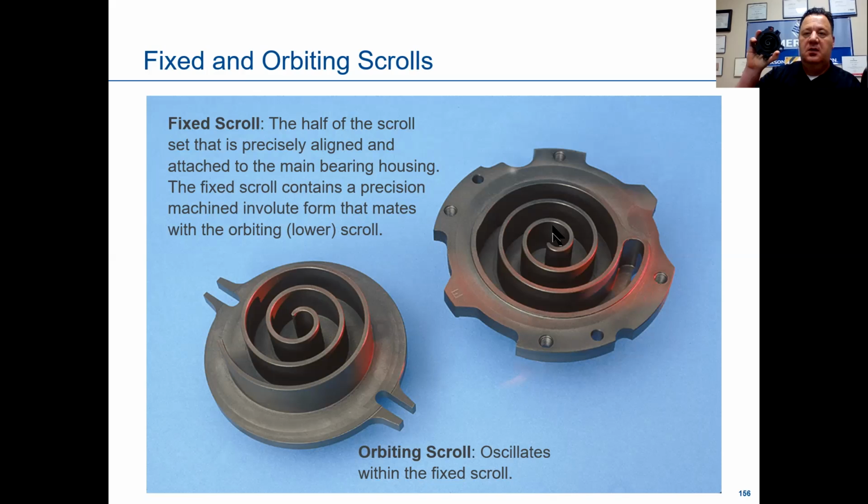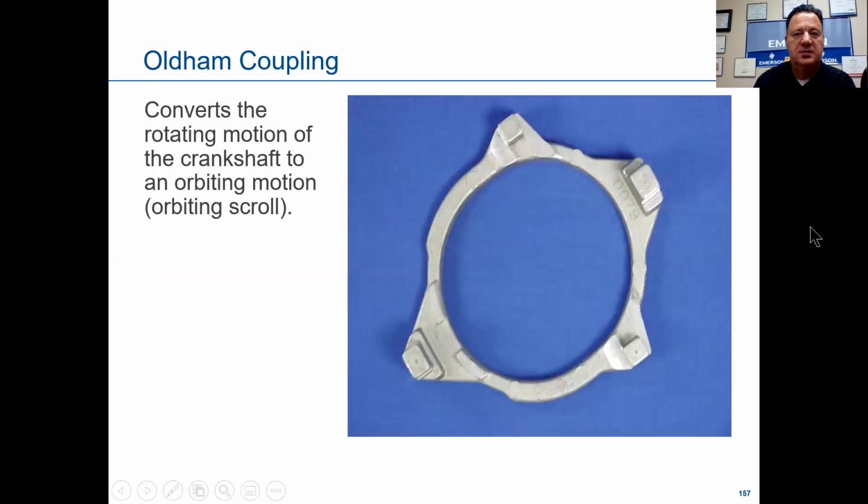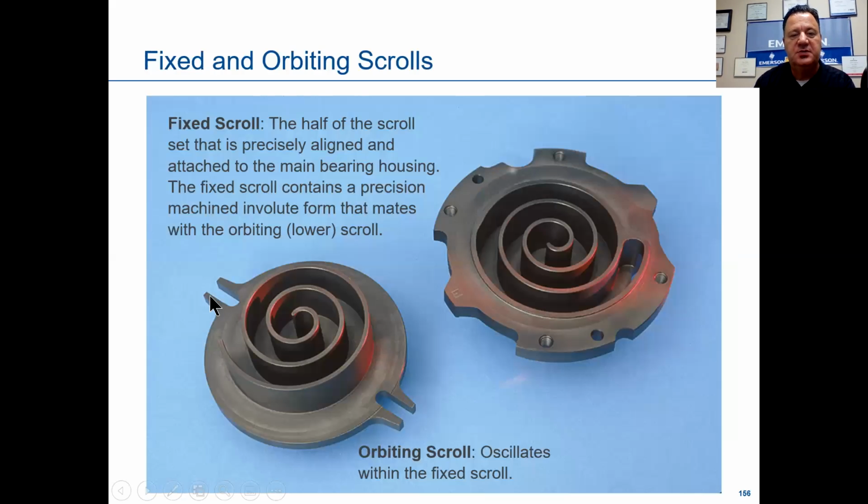Just so you know, I'm not going to go into all the details about the scroll set because this is about modulation, but I do want you to understand some of the moving parts in here. I think it's important for us to have this conversation prior to getting into modulation. The very top of this is your tips, the sides are your flanks. This is the Oldham coupling, and the Oldham coupling is what keeps this aligned. These notches.